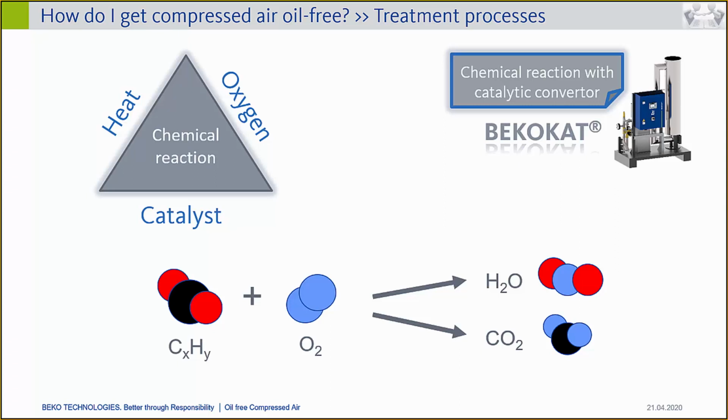And if there is, for example, 24/7 operation on the customer side, then it's very important to consider that any treatment system where the BEKOSPLIT is included needs a redundancy or at least a functional bypass system. By the way, I would recommend integrating a functional bypass system all the time, because in terms of maintenance, you are more flexible, or the customer is more flexible, not having to interrupt production.